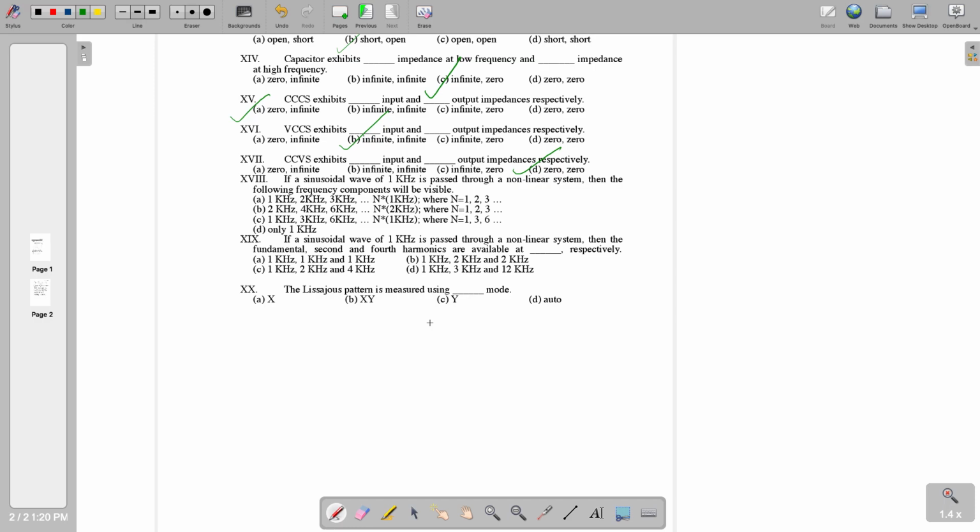Okay, so you are writing all the correct answers. That is the way you are going. I'm thinking A. Sir, if A is correct, it includes BC. Yeah, but I wanted to write down that you are going to see only this many frequency components. So the first one will be the correct one because it will have all the harmonics of 1 kilohertz. Maybe I formed the question wrongly. But you are going to see only these components. In this case, 1 kilo, 3 kilo, 4 kilo are not there, so it's a wrong answer.